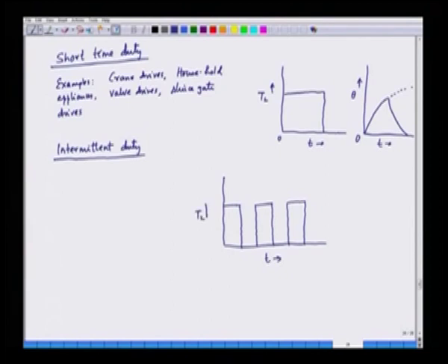So, this is the load torque in the y axis here, and if we see the temperature rise here, the temperature rises in a very interesting way. So, these are basically the applied loads. Theta is the temperature of the motor. Here the temperature rises, then when the load is switched off it falls, then again rises and falls. So, the temperature does not reach a steady value, rather it fluctuates from a minimum value to a maximum value.